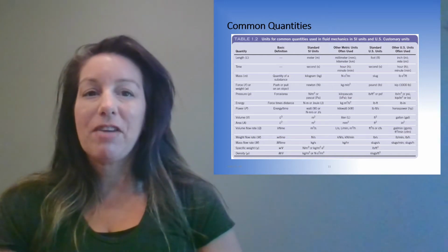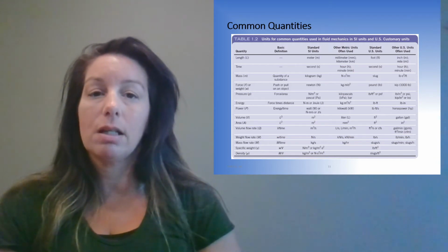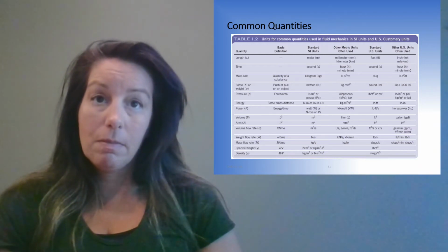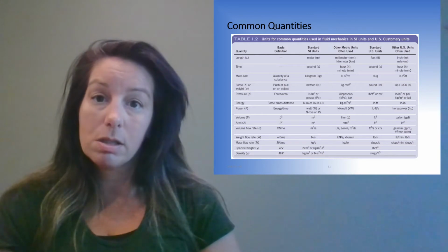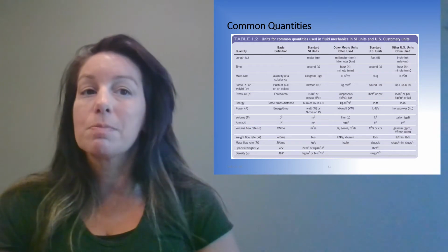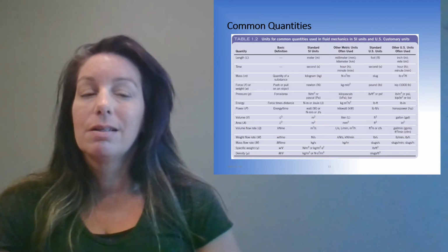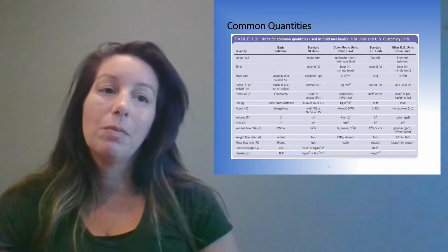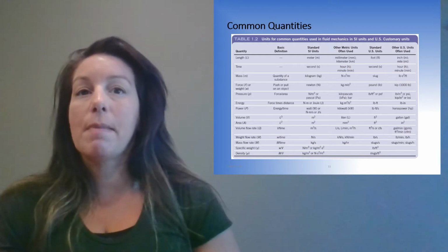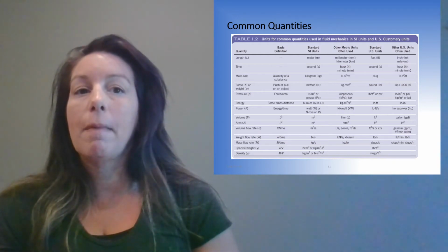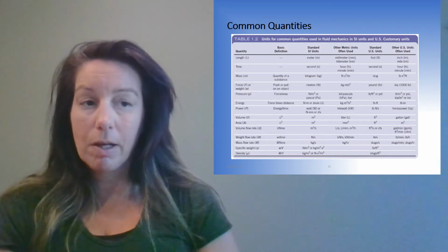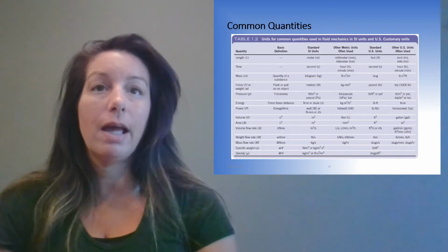Okay. Specific weight is gamma. You'll see this lots. We'll be talking a lot about this. So it's weight or force over volume. So newtons per cubic meter, kilograms per meter squared times second squared, or pounds per cubic foot. And density, rho, which is the mass per volume, so kilograms per cubic meter, or slugs per cubic foot. We'll get into it.